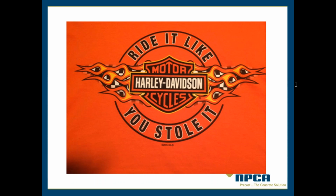What was the outcome of the concrete that showed up at your lab in Cambridge, the one you just mentioned? They had to double batch in that situation, and they double batched one load of water and admix, but not all the other materials. So they essentially ended up with a double batch of admixture, and it put the concrete to sleep. It was a low cement, high slag mix, so easily retarded in the first place. Interesting. Yeah, we had to cook that concrete to make it set up.